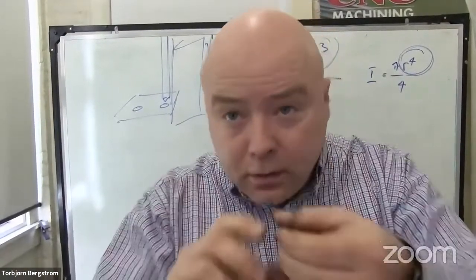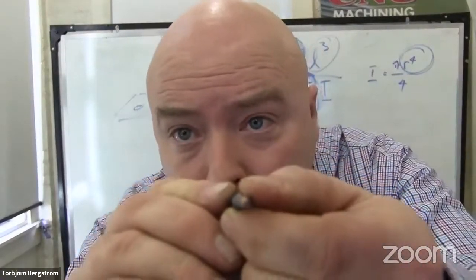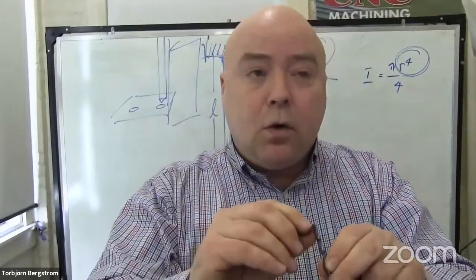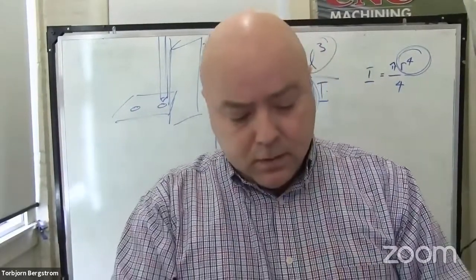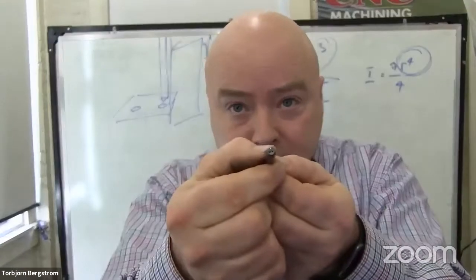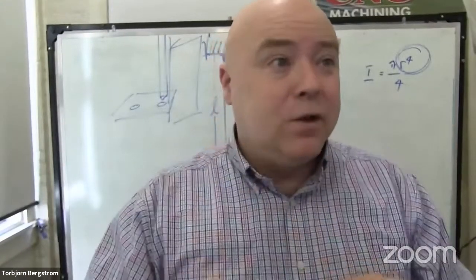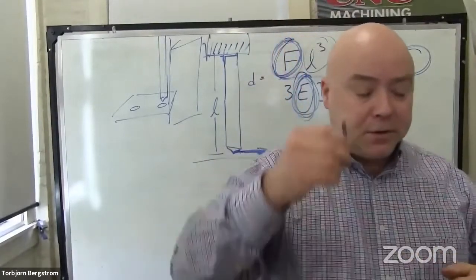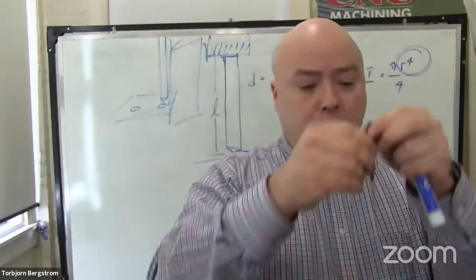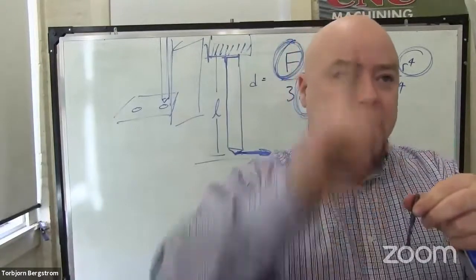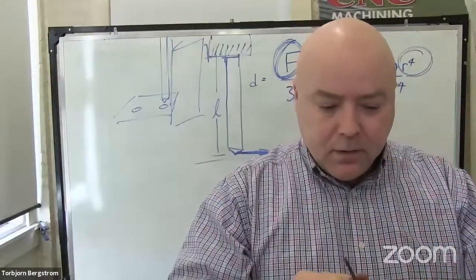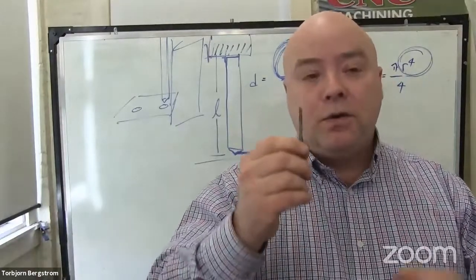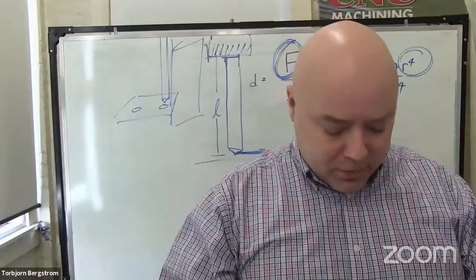This one's really cool too. You probably can't see it, it won't focus that close in. But if it would, you would see that there are 2 little holes in the tip of the drill, and 2 little holes in the other end of the drill. That's to let coolant come out the tip of the drill. So you spray coolant down in the bottom of the hole while it's drilling to push the chips back up out of the hole. This drill is made especially for making holes with a large length to diameter ratio.